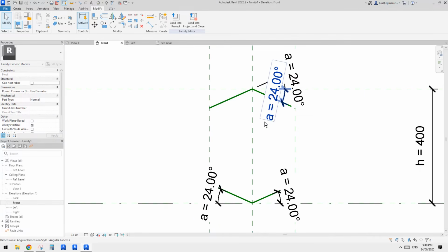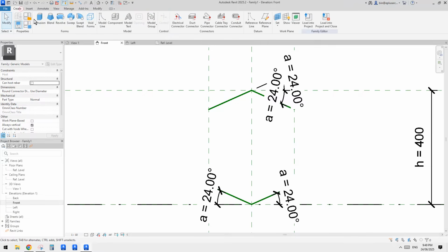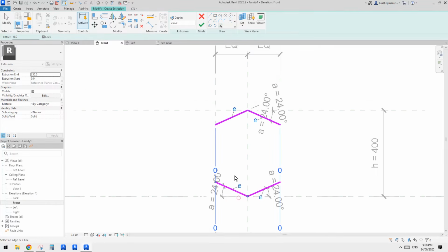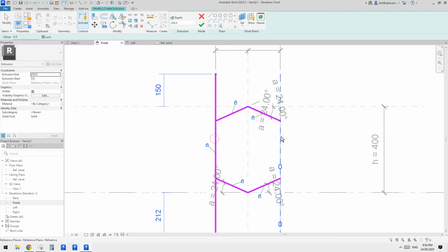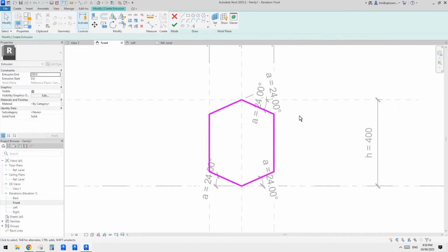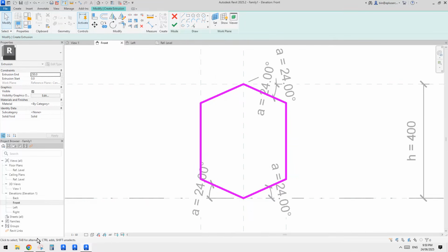We still need that one, but yeah, let's just create the shape. So let's create extrusion. I'll just use pick line and then tick this box, lock 1, 2, 3, 4, and we can just pick this reference plane and we can just trim. Okay, so TR, trim. So it looks like that's enough, and then we will add some more because we need